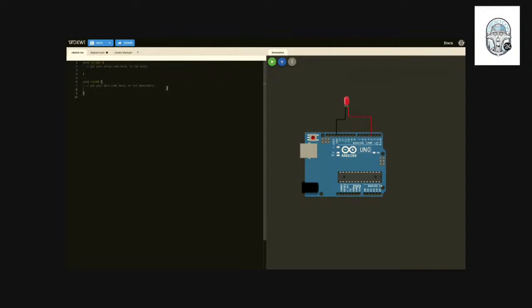We're going to have to enable this pin. So the first thing we could do is say digital write, which is going to write to a pin, and we selected pin 3, so we set pin 3 to true. We can say true, or 1. It's the same thing. If we run this, it's still not going to do anything. Oh, no, never mind, it's set to output.